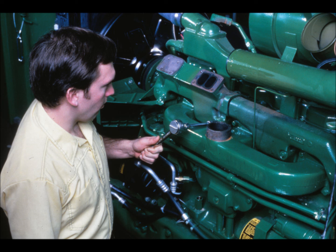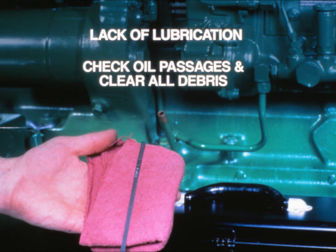Identification of primary and secondary failure modes is an important part of turbocharger failure analysis. Often the turbocharger failure is secondary, and the primary failure mode is in the engine. Identification and repair of the primary engine failure is critical. The following guidelines will help determine the engine repairs that are required based on your turbocharger inspection. Specific repair procedures are covered in the appropriate technical manual.